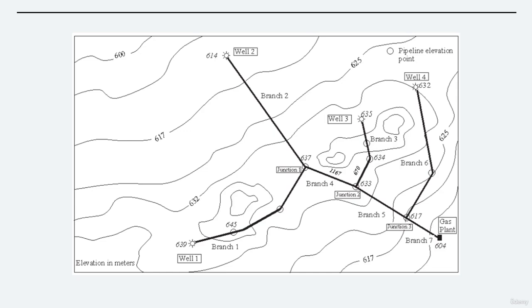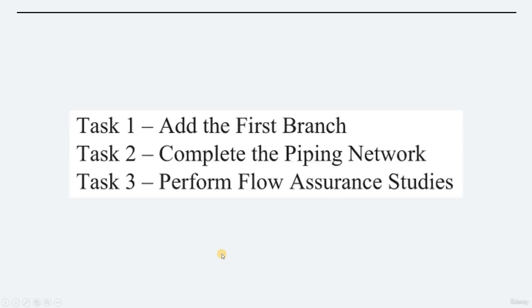Flow lines extending from the central site to each of the individual wells are modeled in Aspen HYSYS using the pipe segment operation. Since the plant is located in an area with mixed terrain, the elevation changes must be accounted for in the pipe segment operations. An insulated Schedule 40 steel piping is used throughout, and all branches are buried at a depth of approximately 1 meter. Mixer operations are used to model mixing points where flows from remote wells are combined in common lines.